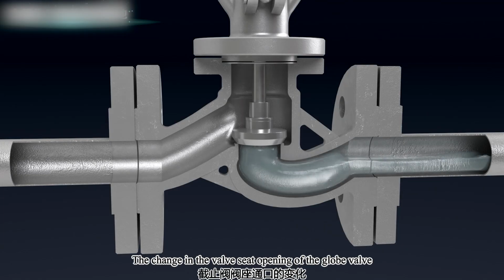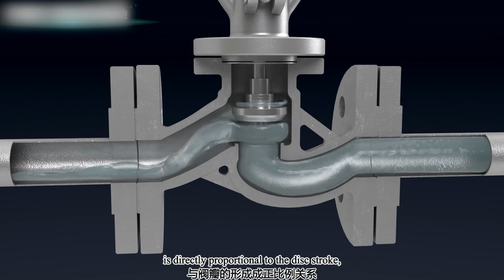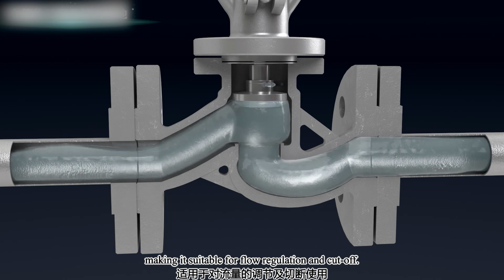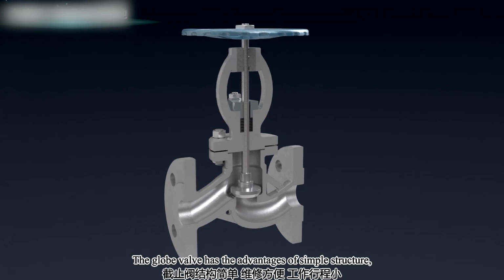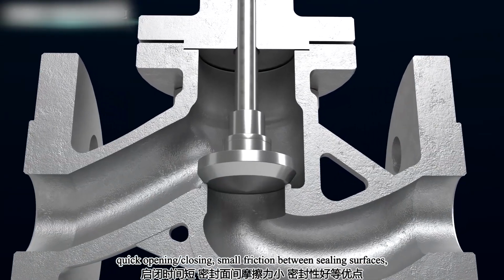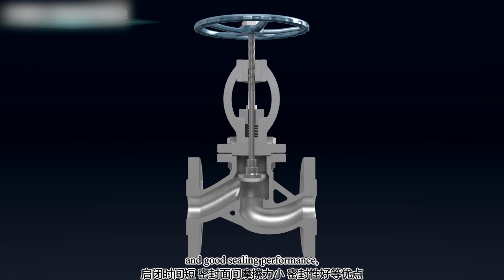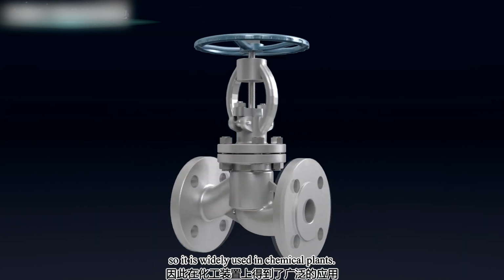The change in the valve seat opening of the globe valve is directly proportional to the disc stroke, making it suitable for flow regulation and cutoff. The globe valve has the advantages of simple structure, convenient maintenance, short working stroke, quick opening or closing, small friction between sealing surfaces, and good sealing performance, so it is widely used in chemical plants.